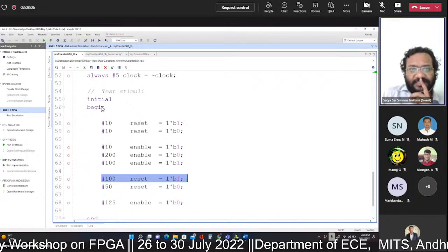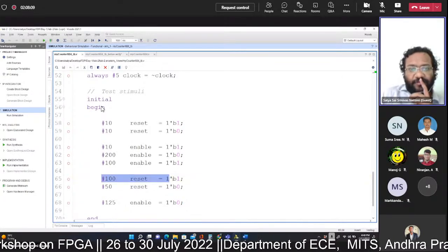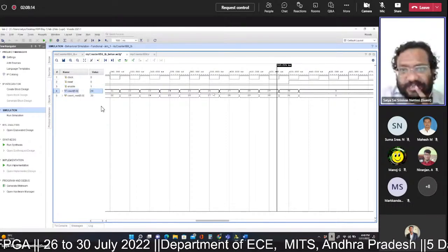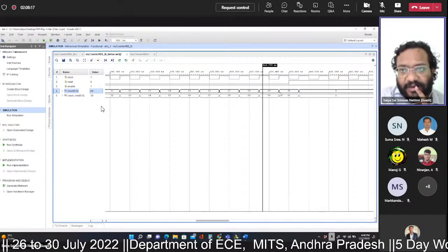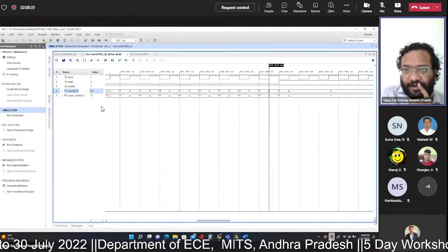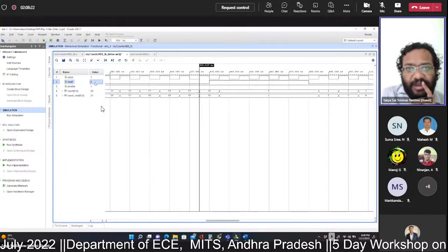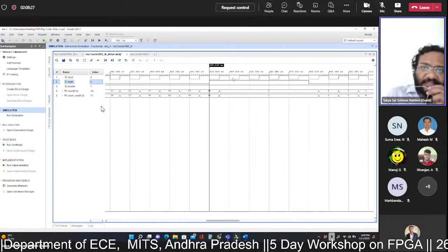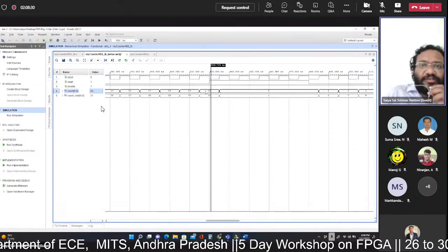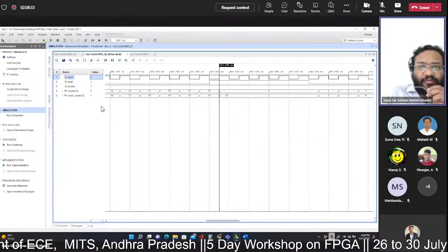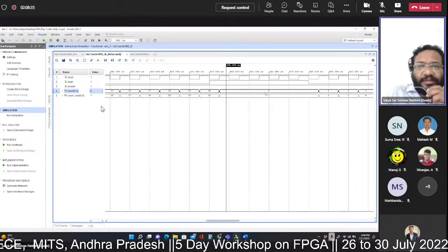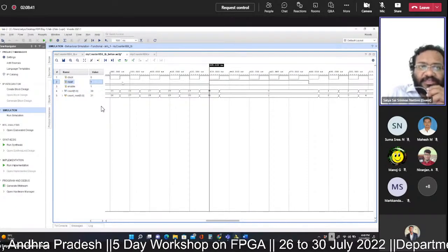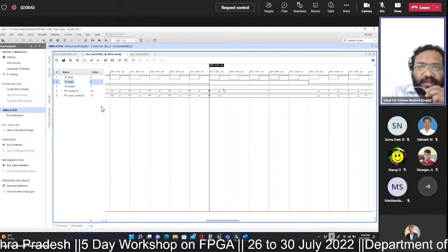Since it has not reached the maximum count value, in between we are resetting the counter. So at the time of counting, it has counted 26, 27, 28, 29, 30, and it is still in that process. After counting the value 30, we have made the reset high. Soon after making the reset, in the next clock cycle, instead of 31 coming after 30, we got a value 0. That means the counter has abruptly reset. The reset was given high priority and the counter has stopped.